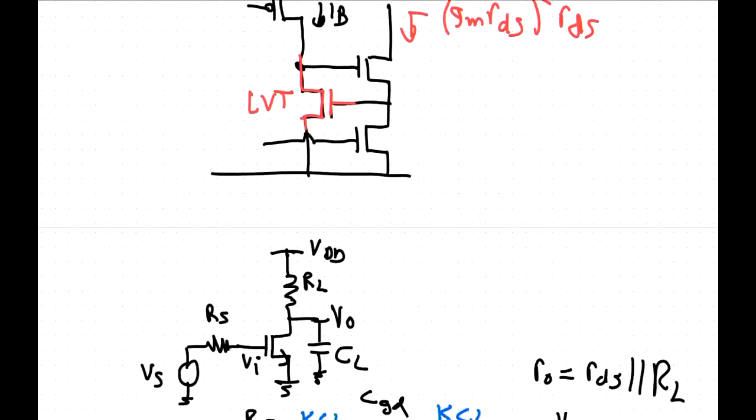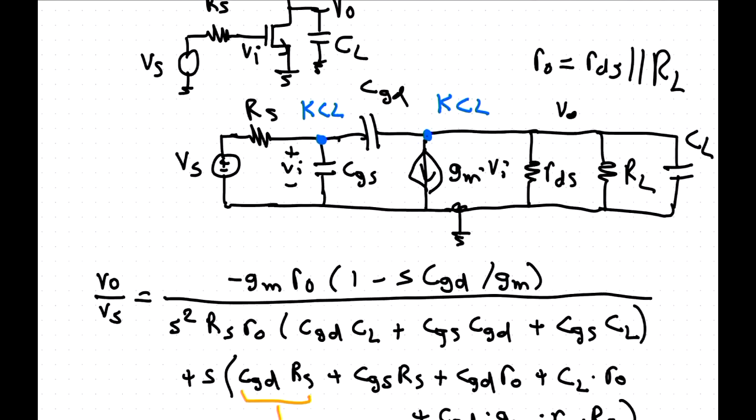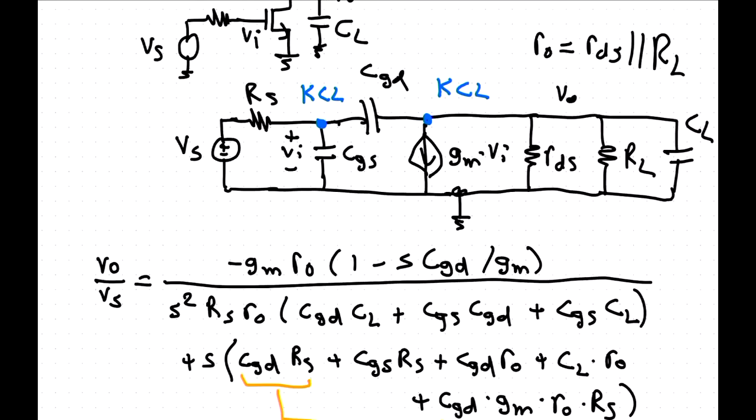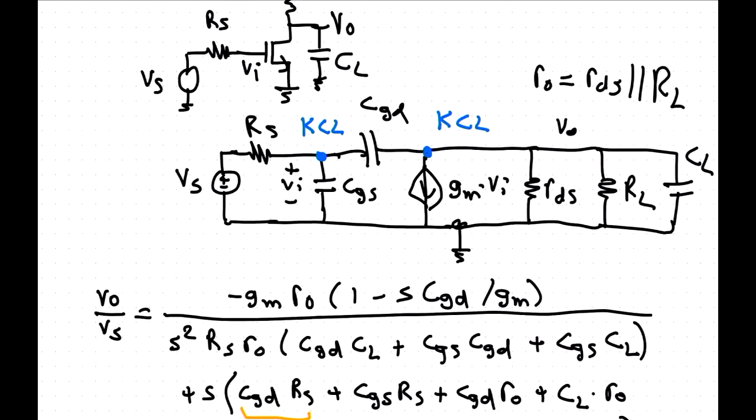Okay. We looked at high frequency analysis. We didn't actually do this in full because it's tedious. For the common source amplifier, you boil it down to a small signal diagram that looked like this: a two-node equation. You boil an op-amp down to the same circuit, I should say. A two-stage op-amp you normally analyze using the same circuit.